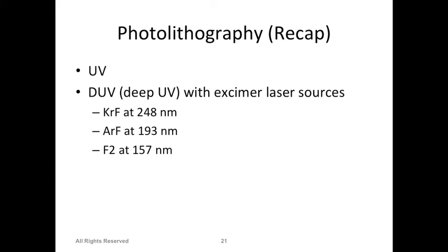You can also use immersion lithography, right? Where do we have to put oil or water if we want to use immersion lithography? Instead of doing the whole process in air, if we put water or oil, we can improve the resolution to some extent, right? Do you know why? Because water and oil have a higher index of refraction than air.